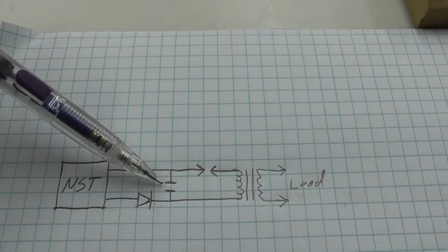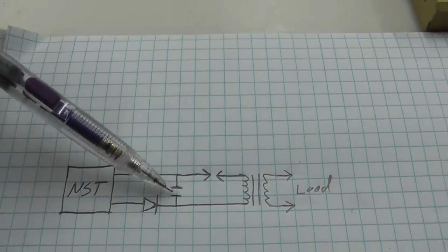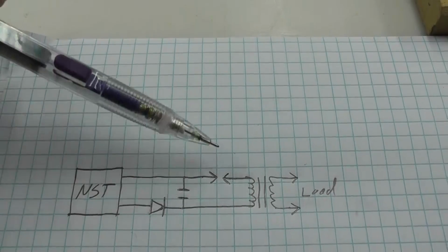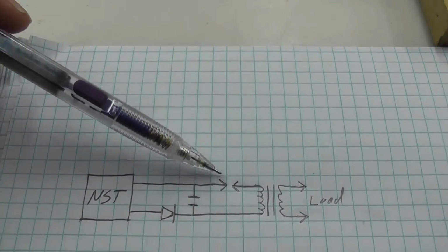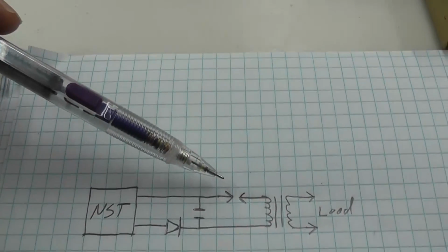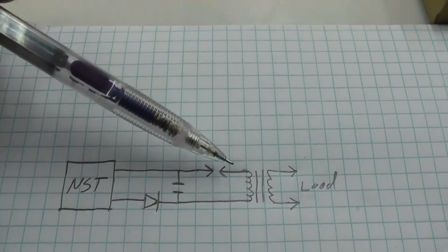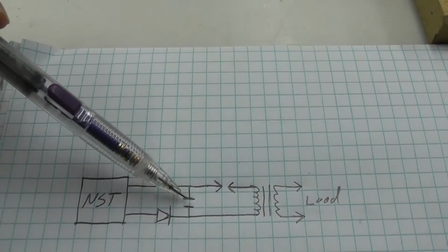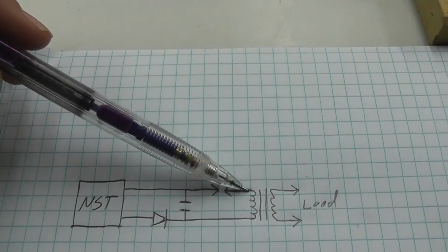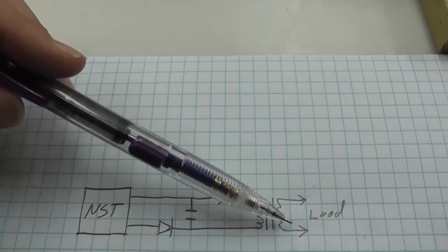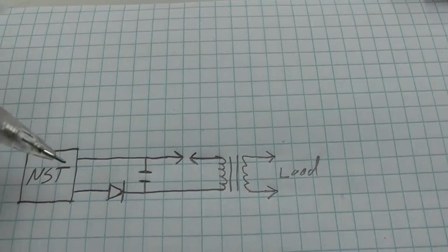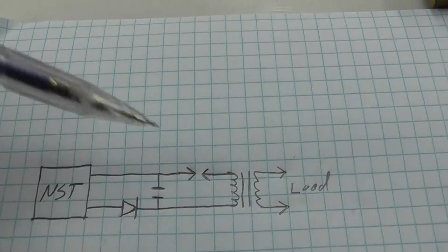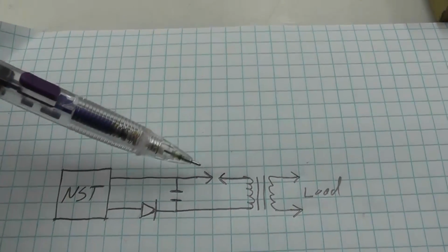Then I can tune the capacitor, which you kind of have to do at the same time, but the capacitor here determines the frequency at which that's going to jump. So the smaller the capacitor, the higher the frequency. The larger the capacitor, the lower the frequency. And then the energy that's dropped out of this instantaneously collapses the field here, which induces your power on this side. Now I think this is mostly correct here. Now you're probably saying, well, this circuit is completely different, and you're right, it is.